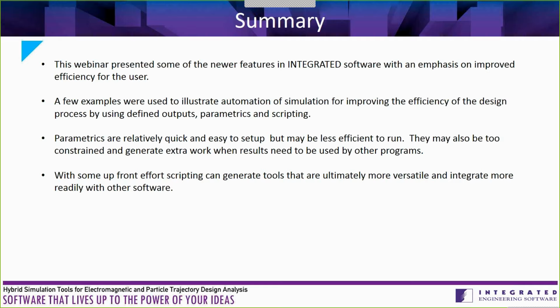We've provided a few examples to illustrate automation of the simulation through defining outputs, parametrics, and scripting. And a quick comparison of the two, if you're going to do something very quickly on one model that's simple variations of the existing design, do it parametrically. That's very fast and easy.